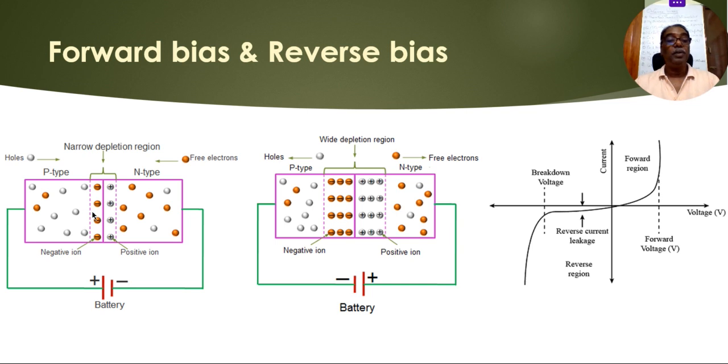When the diode is in the forward biased condition, the width of the depletion region normally decreases and the charge flow is possible if the applied voltage is greater than a voltage called a knee voltage. This voltage may be around 0.3 to 0.4 for germanium and 0.6 to 0.7 for silicon.